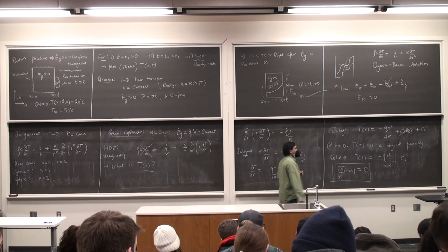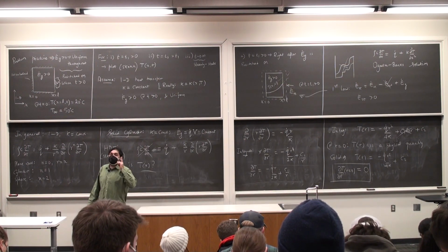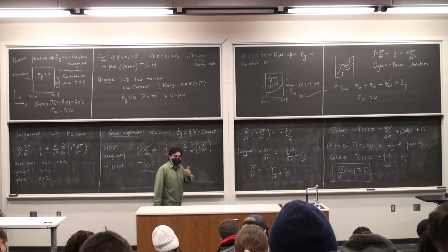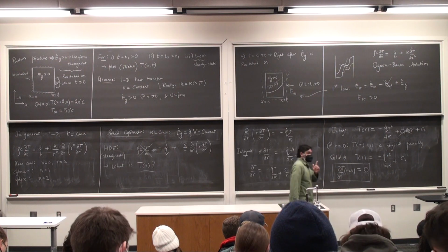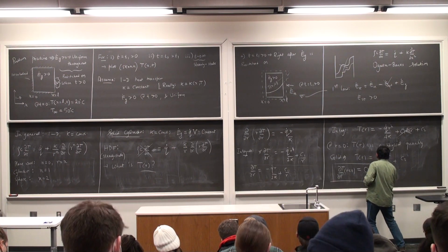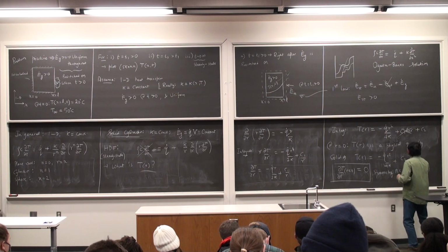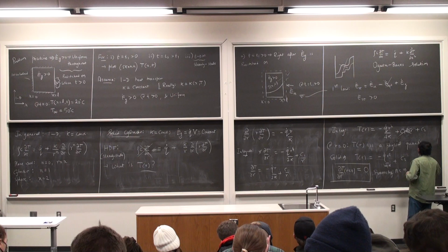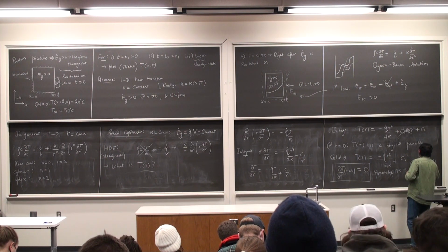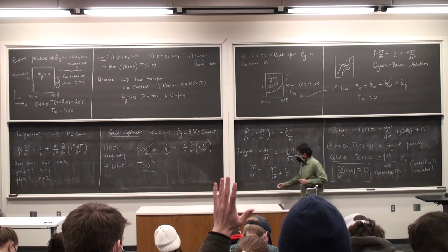And this is called the symmetry boundary condition, which tells you that the center line of a cylinder is always insulated. It's an isothermal surface, temperature is constant throughout the length of the cylinder, but it's also insulated. Okay, so this is a symmetry boundary condition, which tells us that the center line is insulated. This is for a solid cylinder only, please.